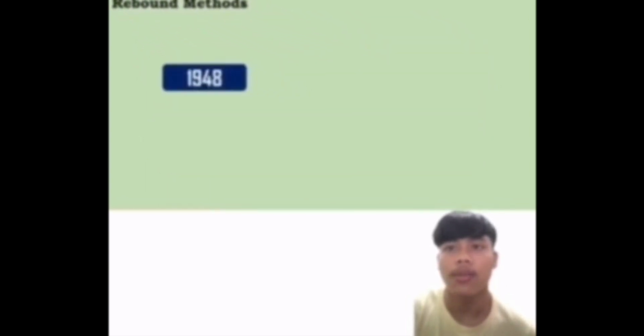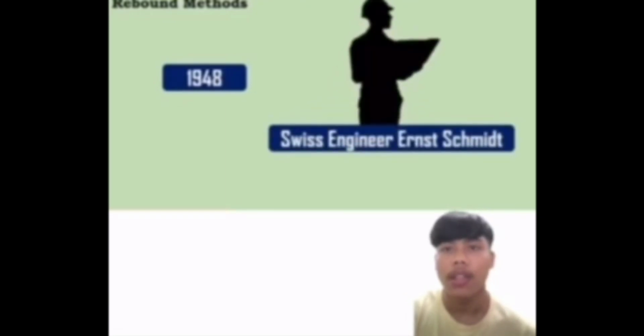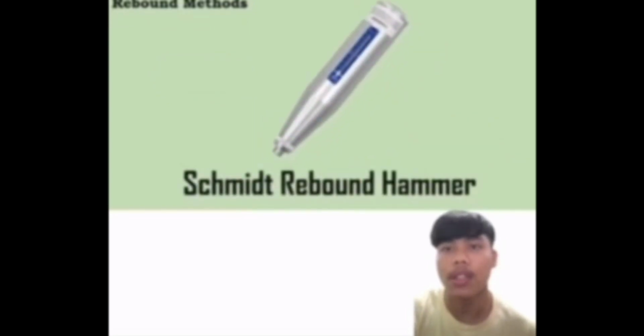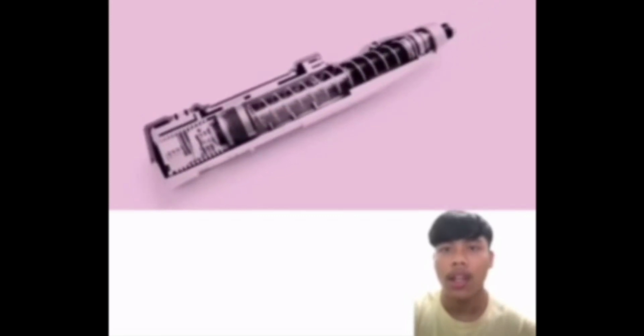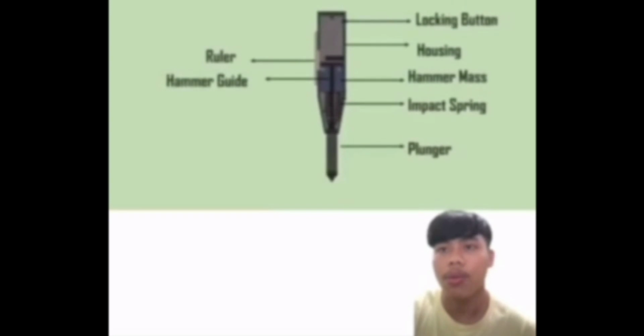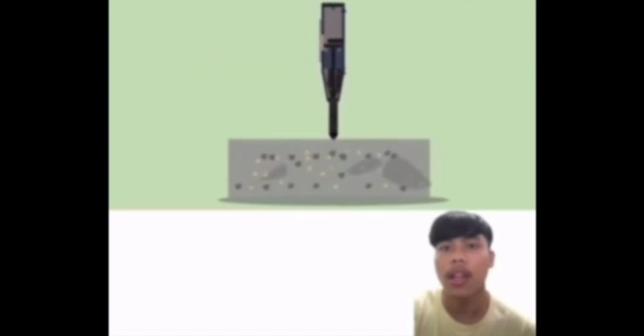One of the tools that can be used for research purpose, especially for soil investigation, is the Macintosh probe. The Macintosh probe test is carried out to determine the strength of the soil. A Macintosh probe is a lightweight portable penetrometer that is designed to investigate the soil bearing capacity. It is a lightweight dynamic penetrometer and a considerably faster and cheaper tool than boring, particularly when the depth of exploration is moderate and the soils being investigated are soft or loose.